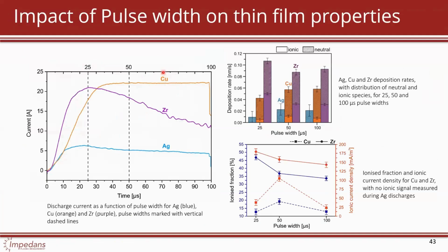Now, yeah, if you have an argon plasma, that may interfere. What helps with that is if you have the source pretty far away from the substrate, because the plasma is really confined, so the argon is confined, and it should only be the sputtered metals that make it. So that's one way of filtering the argon out a little bit. Argon does have an impact.